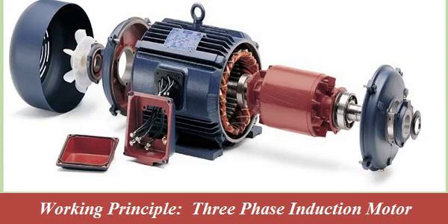Stator. The stator is the stationary part of the motor and is composed of a stack of laminations with evenly spaced slots. It contains three sets of windings, typically distributed around the inner periphery, which are electrically displaced by 120 degrees from each other.